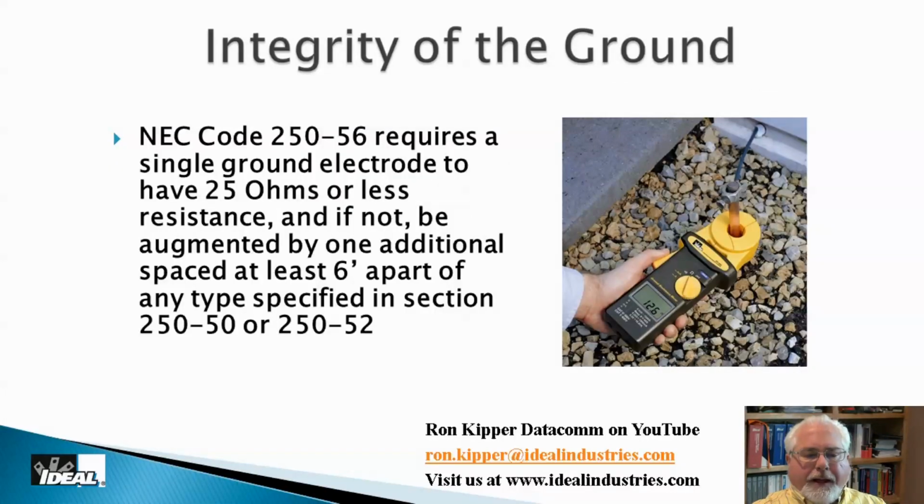And you can't take this with just a typical ohm meter. You've got to actually have an earth ohm resistance kind of meter, what they call a megger type tester. And there's several variations of meggers out there. And it's interesting, the code book says if you drive one ground rod on the outside of a home, Mr. Electrical Contractor, you're required by code to actually measure the impedance of that ground, which should be under 25 ohms or less, and usually it's quite a bit under that.